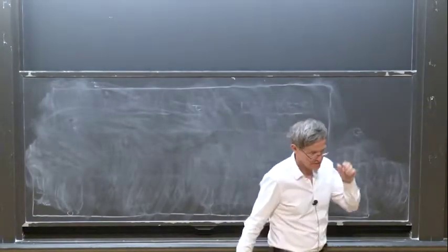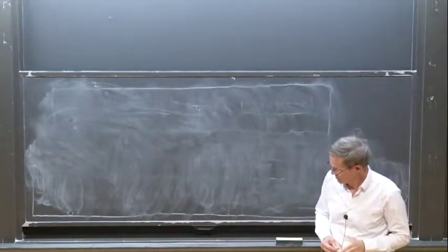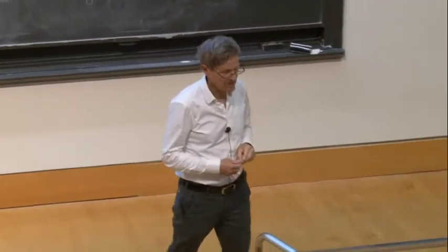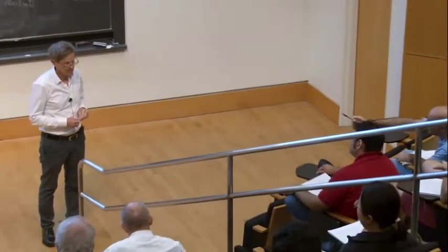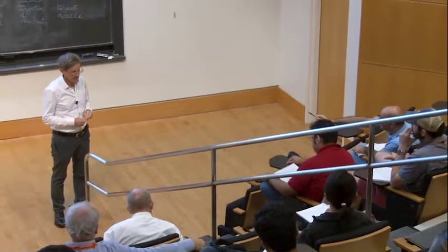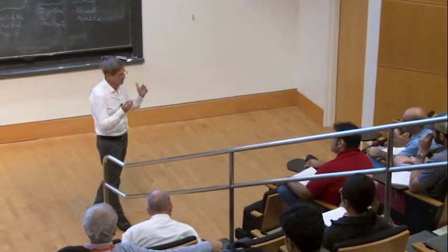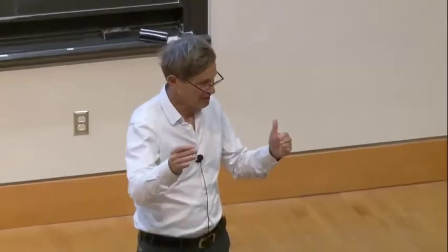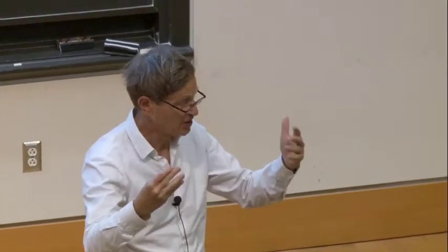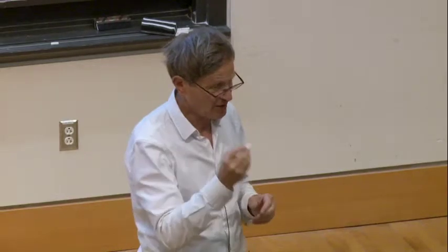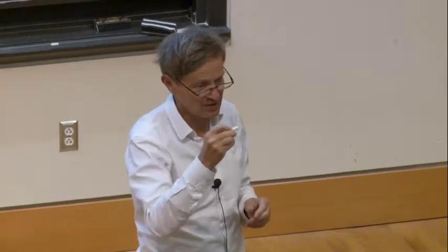Just a question regarding the function G. A function of x and t is equal to G0, right? Yes, this is constant. So if this is a kind of boundary condition, x should be specified as a position, right? No, it's not a boundary condition. You say that the flame is a contour among all these. G is a function of x and t, and you consider that the flame is one of the isosurfaces. So you say the flame is G of x and t equal to G0.